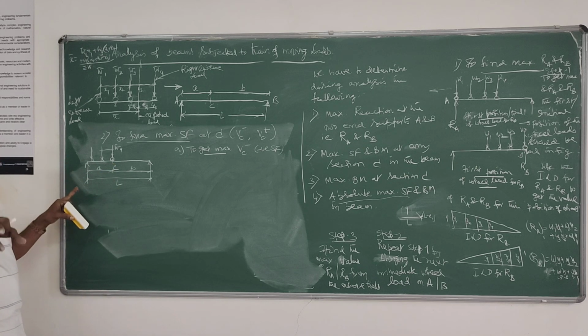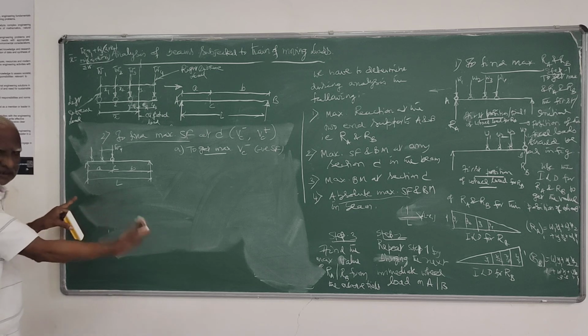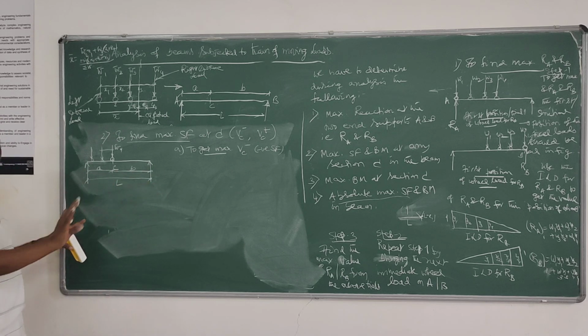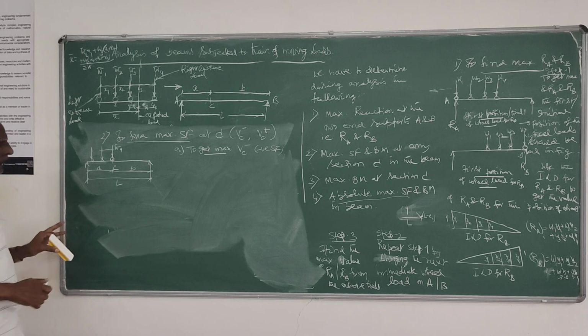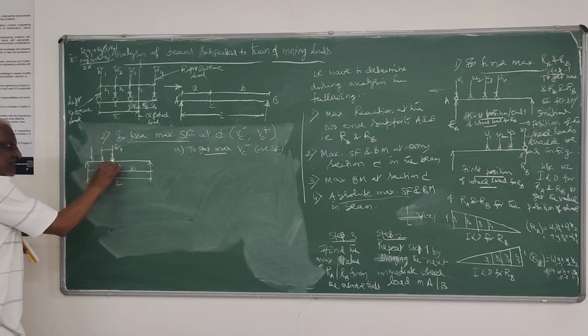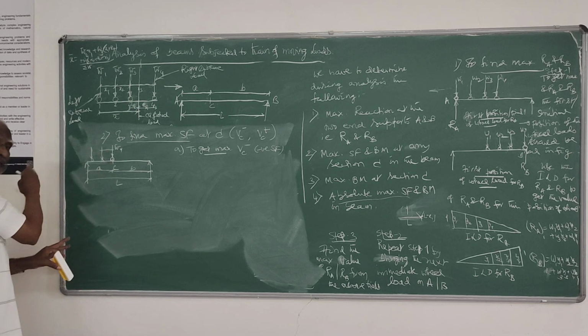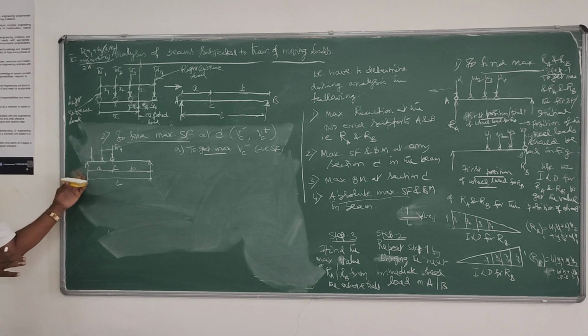So that's why I told you the limitation is that we cannot use the shortcut criteria. So we have to adopt this trial and error process only. That's why I told you, you stick to that process only. You first place the right extreme wheel load at this section, then you arrange the other wheel loads which are possible. That only you have to arrange.